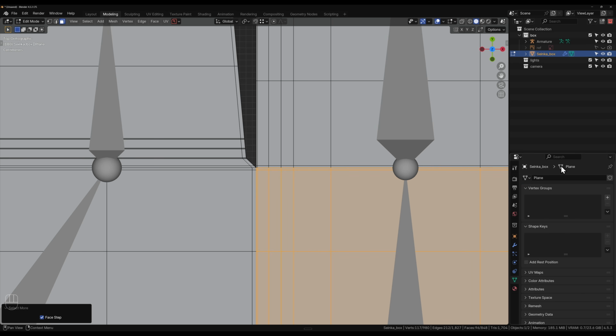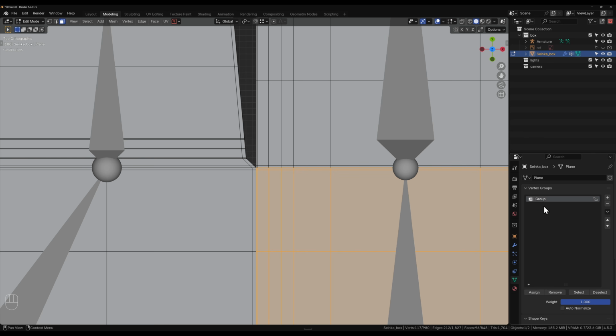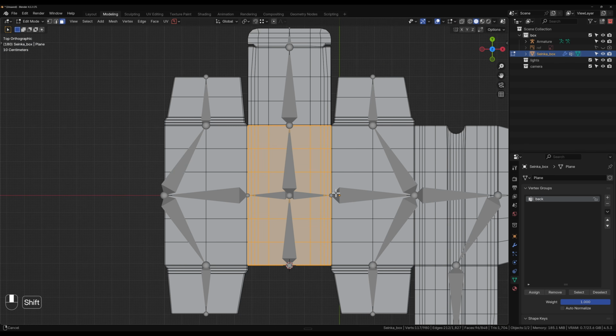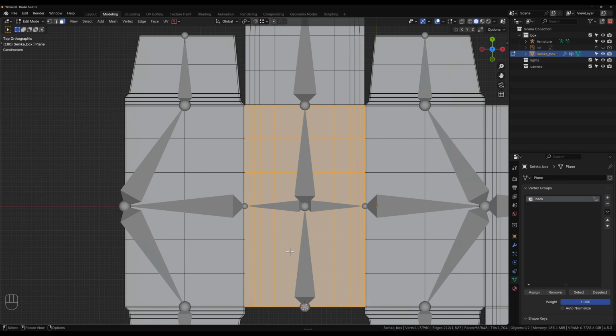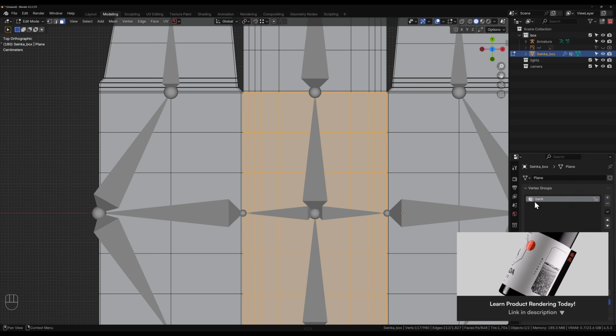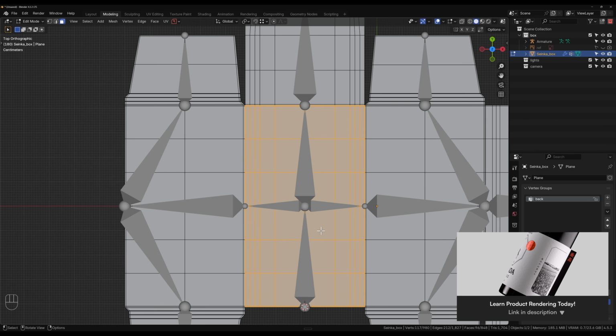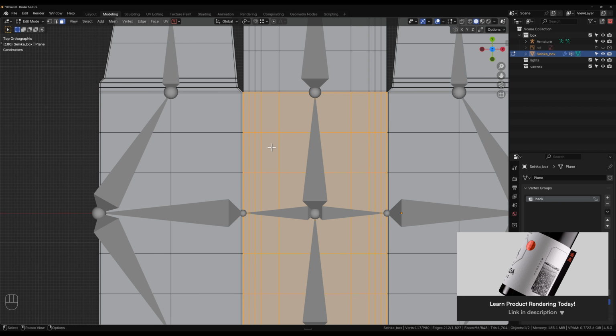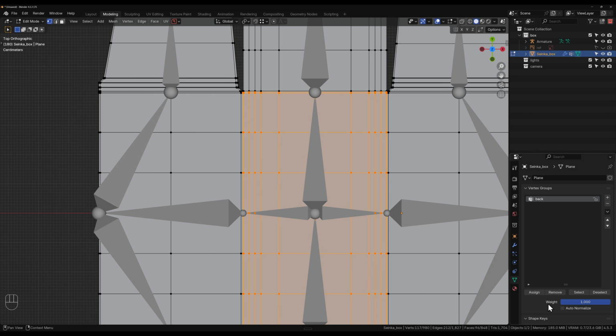Anyway, it's got vertices in here, the vertex groups. I'm just going to add a new vertex group and call this one back. Remember that you have to remember these names because we're going to actually rename the bones to the same names so that they get assigned to each other. So once you have that selection, each vertex, we can add a weight of 1 by assigning it to the group. So hit assign. We'll add it to the group.